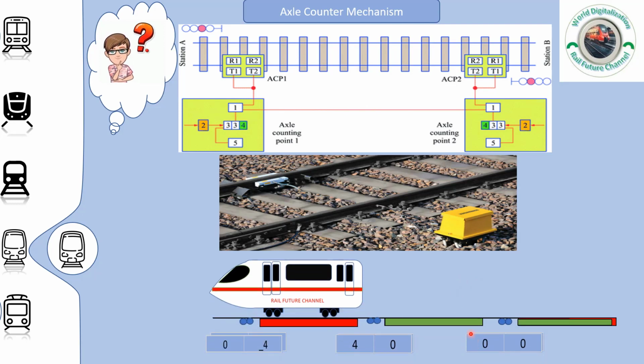As illustrated here, after the train passed over this axle counter, we have -4, and we had at the beginning 4 axles in. So the EU unit, or evaluation unit, will decide that the 4 axles in became out from the other out head, so the section will become clear.